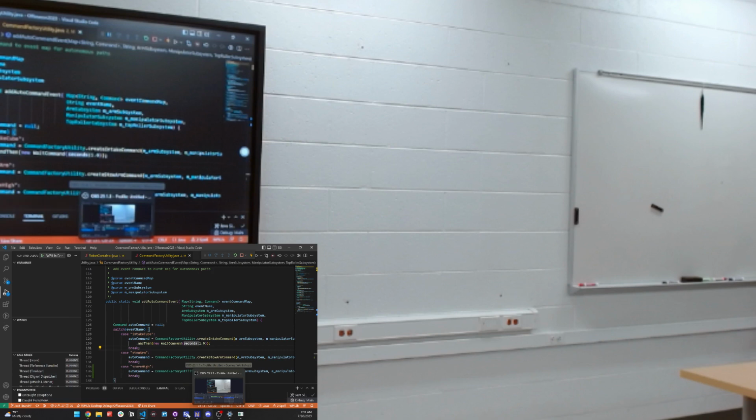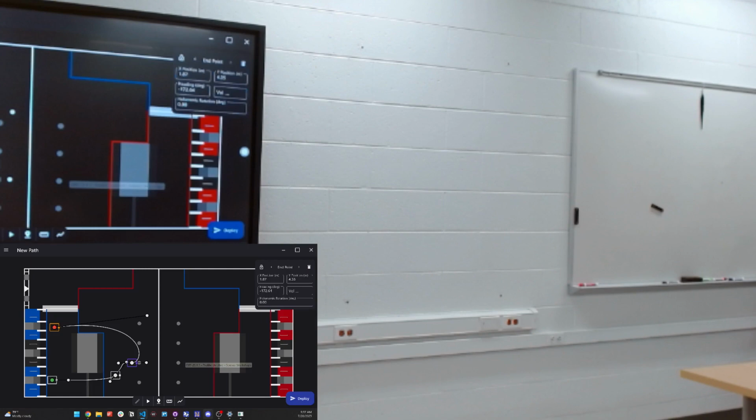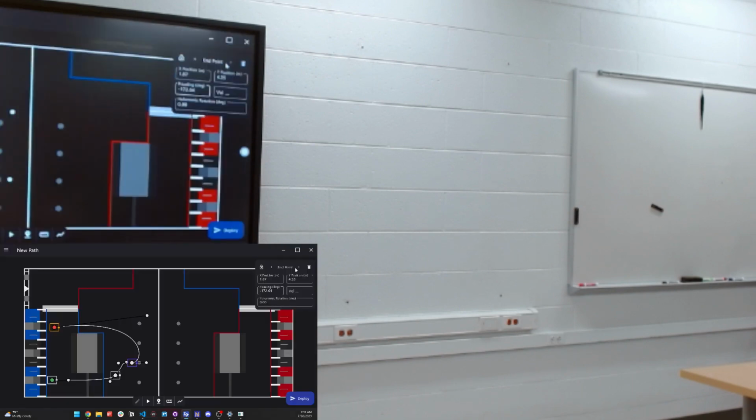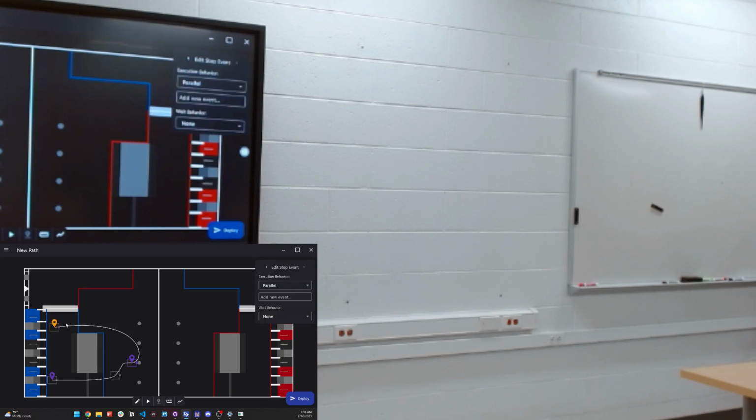It's been useful for us also if you wanted to just not affect the path, just take the event off it, not put a command in there, and the path still runs without an exception saying null pointer or event doesn't exist. It just doesn't run the event. So you can always add the events that you want to do as you test individual ones. Put them in the command event map as you need. We've done that when we haven't finished the arm or the arm's not been tuned yet. We don't want to be flying all over, so we just take our events out and then run the system